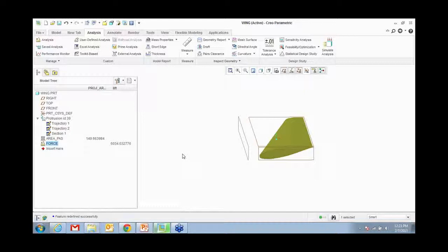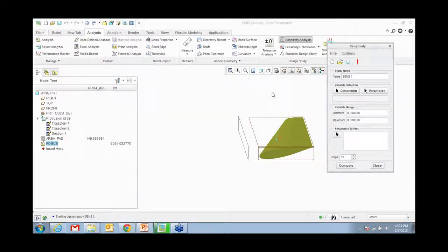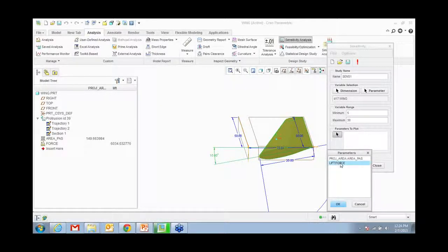You see that you're reading a parameter name XL37, so you want to give it a name, say lift. That's it done. Now, what is the value of lift? If you go 3 columns, feature parameter, if you say lift and say OK, there it is. It's reading from Excel. What can you do with it?